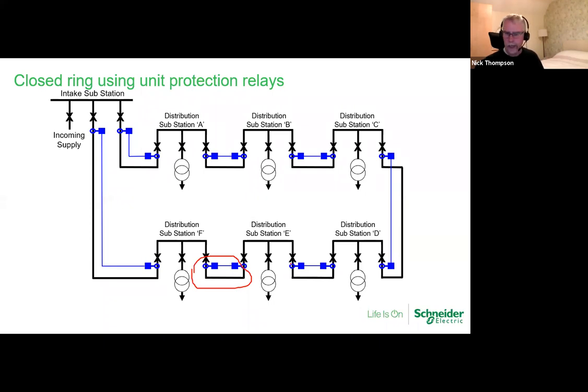So these protection relays are now tied together by this pilot wire. Now, the pilot wire, you would think the best course of action would be to follow the main cable, but that's probably not the best solution, because if our JCB chops through the main cable, it could possibly chop through the pilot wire as well, or the pilot wire only, and then you don't have any protection on your cable. So this is purely cable protection.